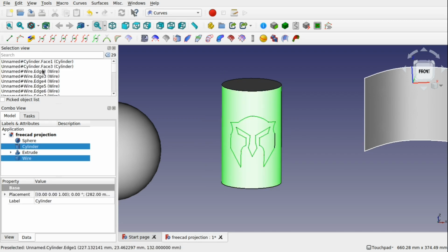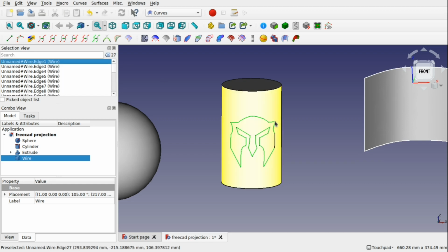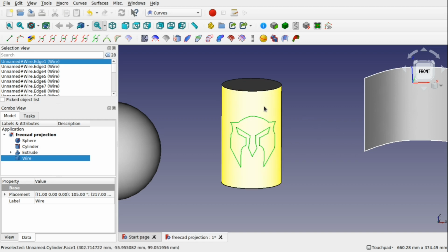And you can see we've got unnamed cylinders come in here, which we don't want, and what we can do is come in here and right click, deselect, so that cylinder's gone now, and I can come back in and control select that edge like so. So we've got those selected now, and then we can make our selection against the cylinder and do the removal.